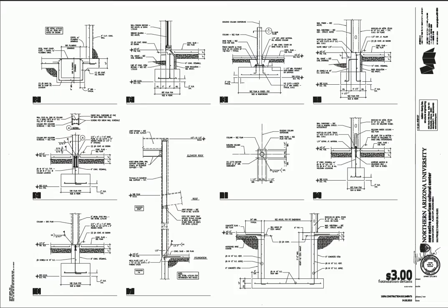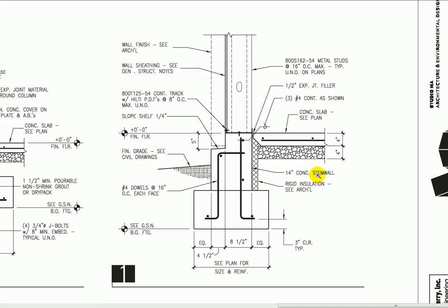So here's sheet S300, and we need to find detail 1. So zoom into detail 1 here. And here's detail 1. And so what we see here is that wall footing. So from above, this was a dashed line, and this was a dashed line here because this one's under soil and this one's underneath the slab. We had 3 lines on the top.